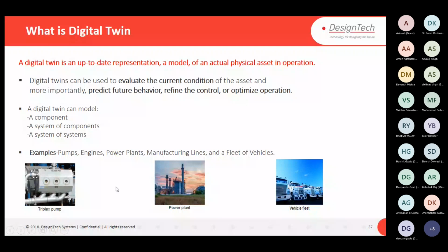Okay, plant, or we can say any component or any machine. So now what are you doing? Suppose you are going to create the virtual model of that plant in the Simulink environment, and you are taking live data using the sensor into Simulink, and you are going to verify how your controller is behaving with the real data. So this is called a digital twin.